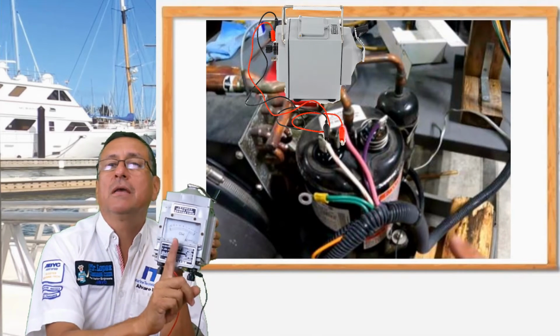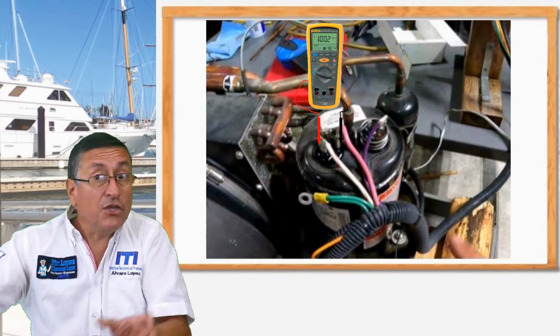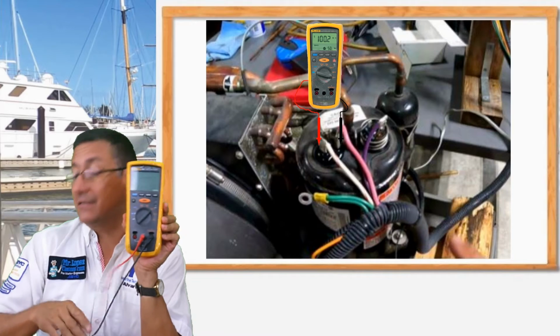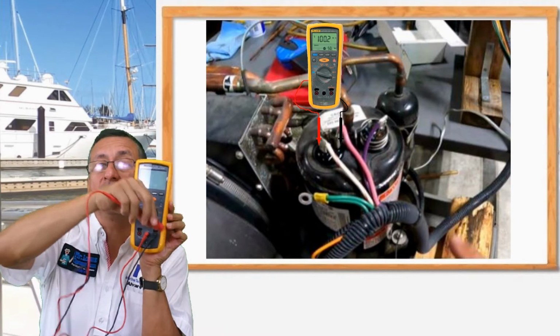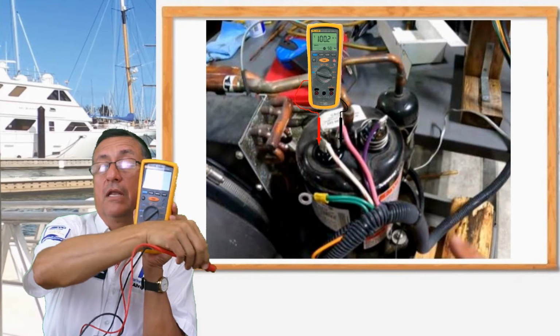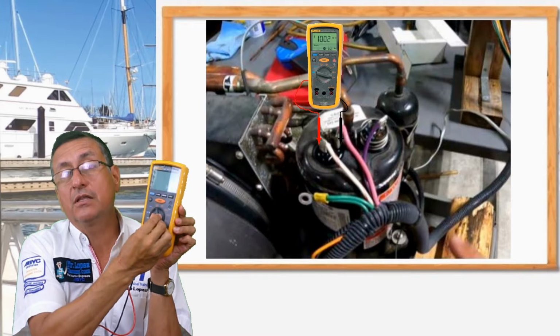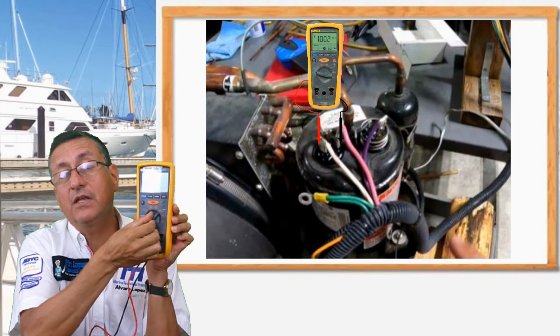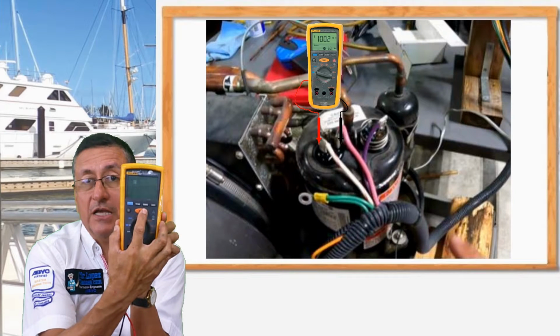Zero is not good. In the middle is not good. This is with the analog multimeter. You can use the digital multimeter, and it's exactly the same. The negative on the case of the motor, the positive in the terminal common or in the terminal start, and you select how much voltage you want to send: 1000, 500, 250, okay, and you apply for 10 seconds,